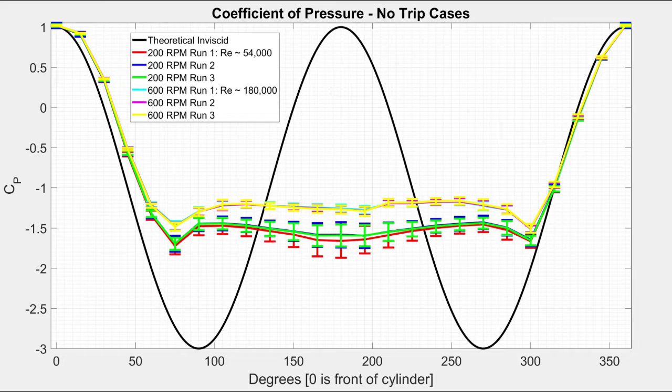The three plots of each simulation are very close together, which makes us confident in our repeatability. But notice that the propagated standard deviations of the lower RPM setting are on average 2.3 times those of the higher speed setting. This is likely due to the large effect fluctuations in the wind tunnel have for lower speed, lower strength flow.